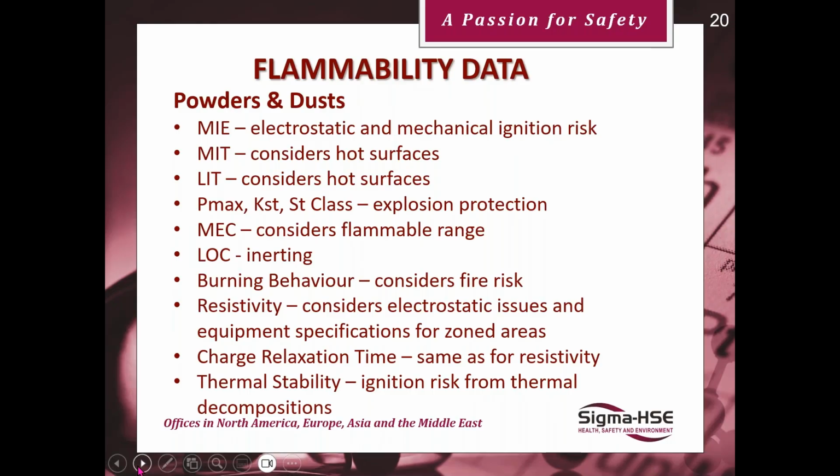You can get minimum ignition energy. This lets you look at the risk of ignition by electrostatic or mechanical spark discharges. Minimum ignition temperature considers the ignition of a dust cloud by hot surfaces. Layer ignition temperature considers the ignition of a dust layer by hot surfaces.